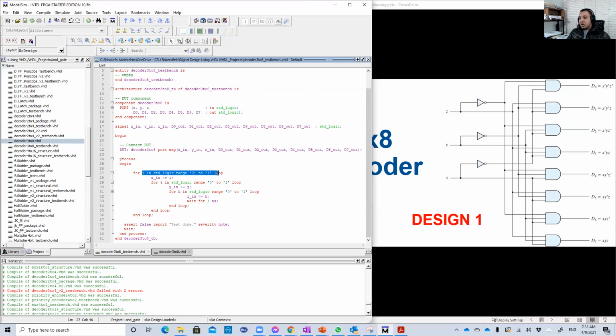And this is the new technique that we learned in VHDL to loop over a standard logic. Here you define a standard logic variable, and you give the loop a range from 0 to 1. Since it's a standard logic, you must put the single quotation marks in here. Then you assign it to the signal xn as a standard logic counter, and you assign another counter to yn. Then a third and last one, k, another standard logic counter, you assign to z. Then let's simulate this.